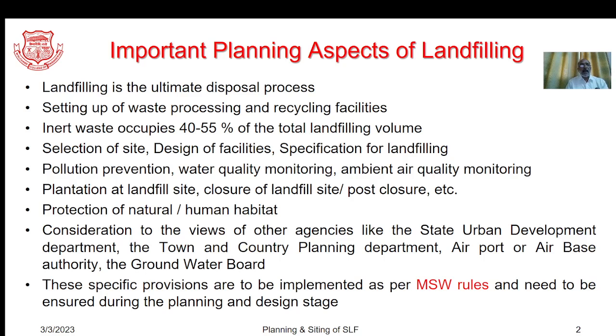So we have to take into account the pollution prevention, water quality monitoring, ambient air quality monitoring. Also, as we discuss the green cover, you have to take into account the plantation at the landfill site and closure of the landfill site as well as post-closure plans, the way we discussed in the previous presentation. Naturally, we are very much interested in protecting natural as well as human habitat.